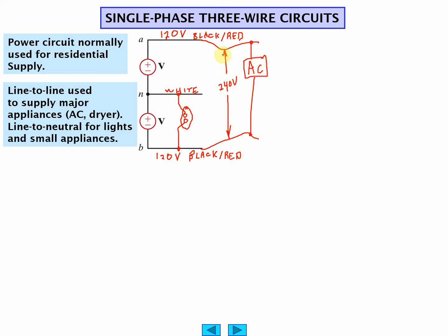And this is typically at 15 amps. Your 120 volt circuit is at 15, but the circuit's capable of delivering more. These circuits can be 30, 40, or even 50 amps. And it depends on the circuit breaker box, what it's wired for.